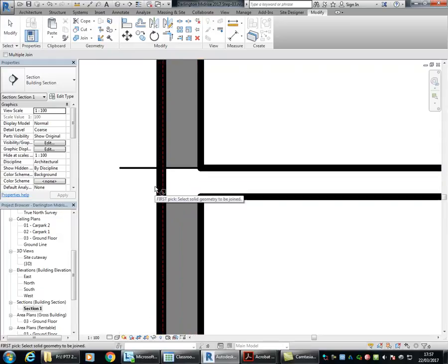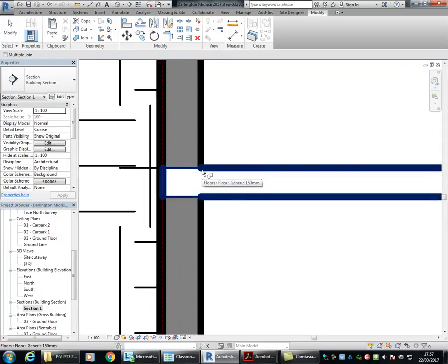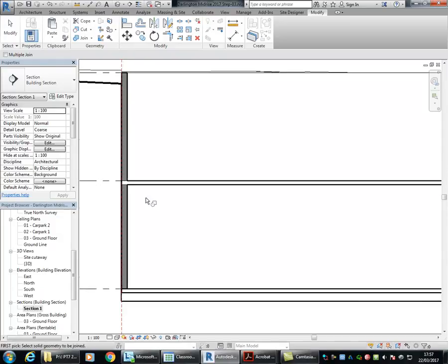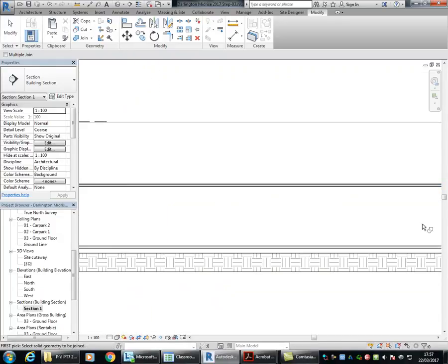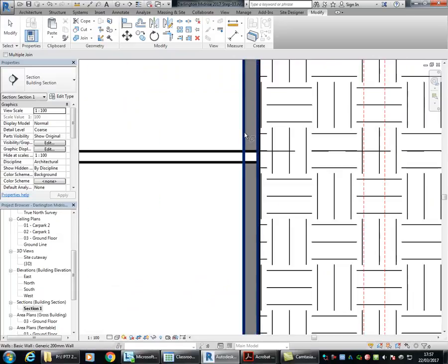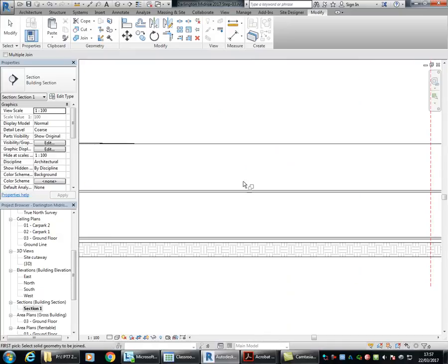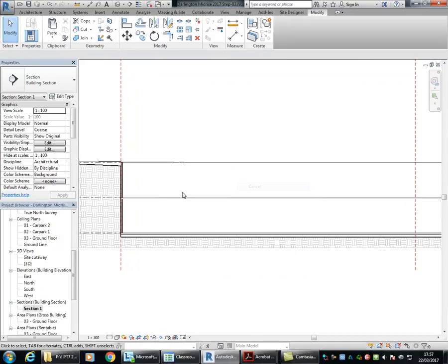Cleans up the geometry a little bit, and you could actually have the floor slab protruding all the way to the outside of the wall in this situation. I think that actually would probably make sense. If it isn't going to do that, the engineer will tell you. Let the engineer make the structural decision. So I think it'd be okay to show it like that for now. Worst case, you'll have to bring the edge of the floor in later. The main thing is that I've got the floor there to give me a base for my ramp.